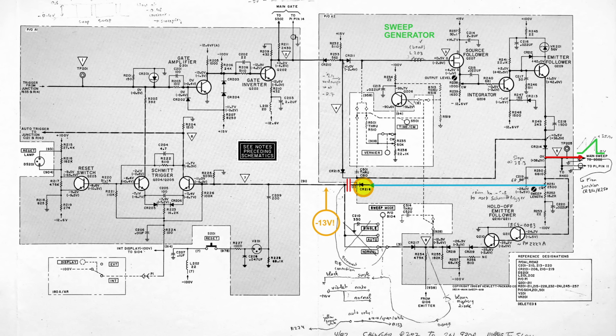And there are only two wires connected to that node. I can smell blood. We are closing in on the kill. So is it coming from here or is it from there? More likely it would be the hold-off circuit that's not working. So it would be coming from here actually before being added on the line by diode CR217. One way to tell is to disconnect the anode of CR217, which would disconnect the hold-off circuit entirely. Hold-off is not really required and does not spring into action until the end of the sweep anyhow, so maybe